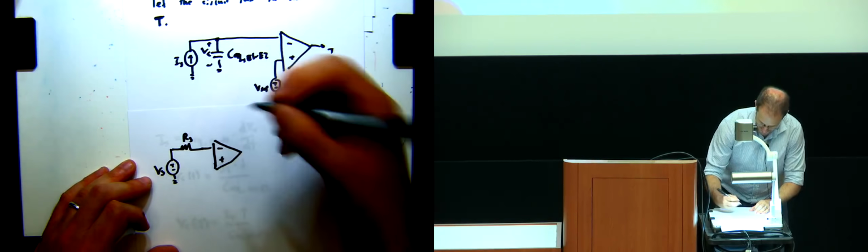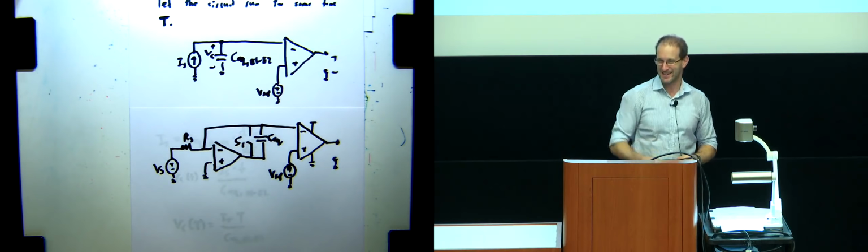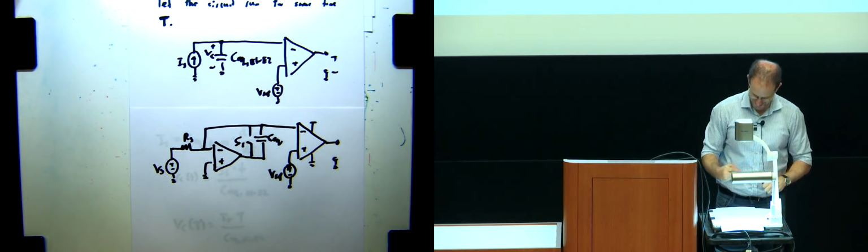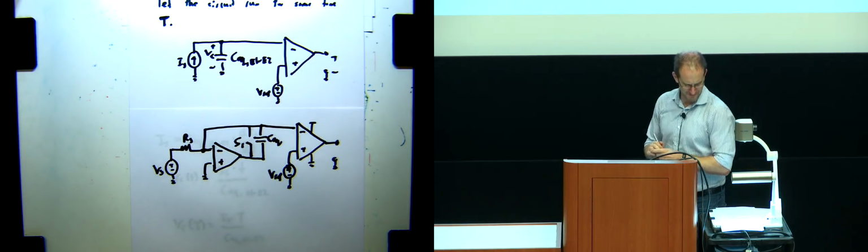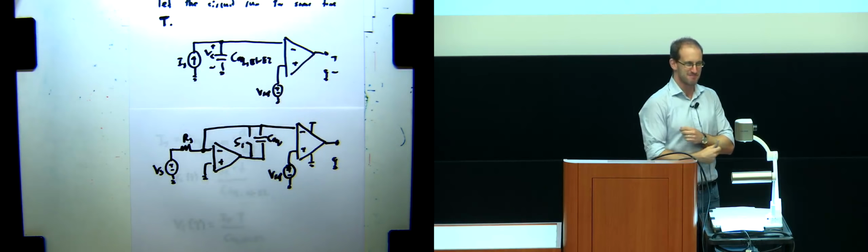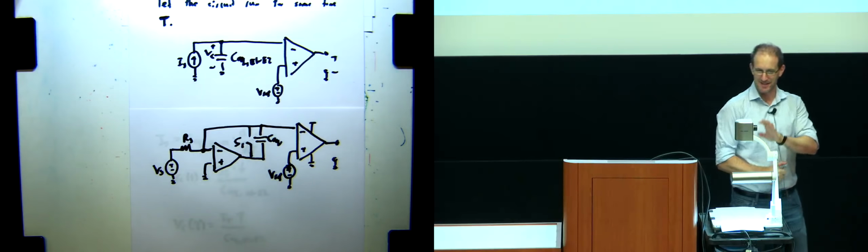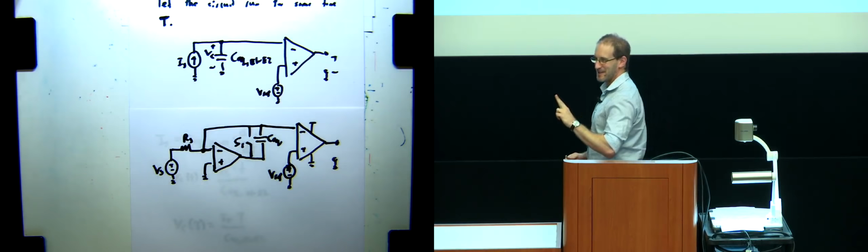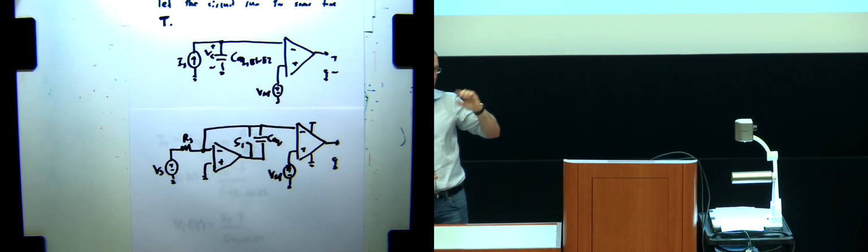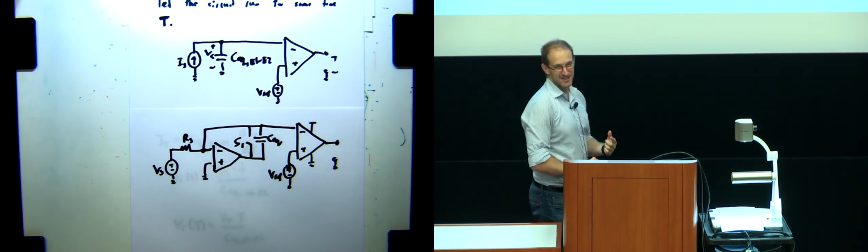You basically said it. I just want to be much more specific. I don't think the current here is going to change. I'm making Vs a constant for right now. Let's not worry about something more sophisticated. What did we say? There were two important caveats when we used this op amp as a current source, right? One of them was the negative feedback, which we've already checked. If I connect a capacitor, fine, it's a negative feedback. There's this other one that I told you was going to be subtle, and that you were going to see what the problem was when you actually connected into the sensor. That's the one that's important.